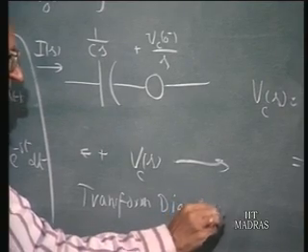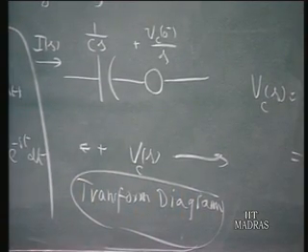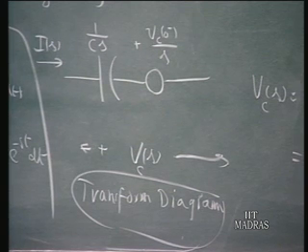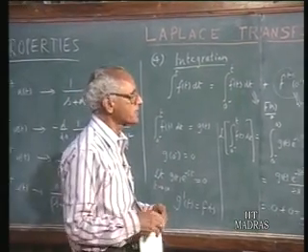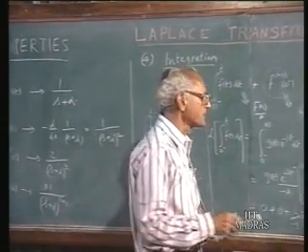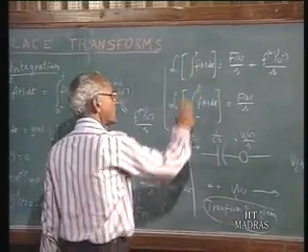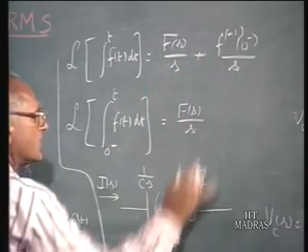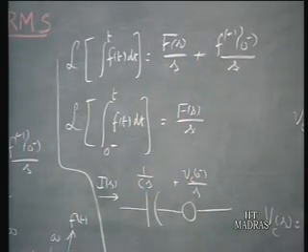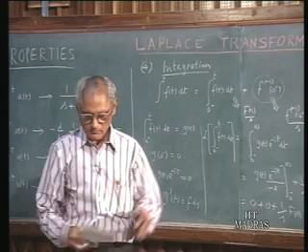In the same way as we have derived it for the case of an inductor, an equivalent parallel form of a capacitor in parallel with a current source can also be derived. I will not do that, I will leave it as an exercise for you, that it can be drawn up in a similar fashion as we did in the case of an inductor. It is very important now to see that you must distinguish between these two formulas, and when you have an initial charge on the capacitor, that is equivalent to a source here, which represents the initial charge on the capacitor or the initial voltage across the capacitor.